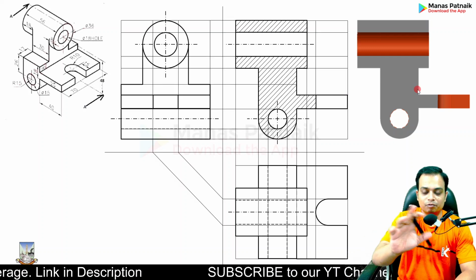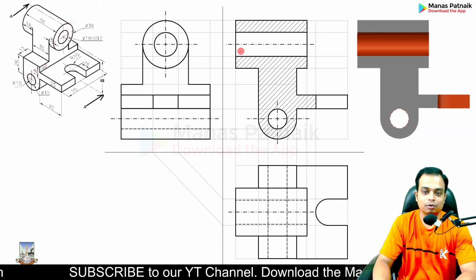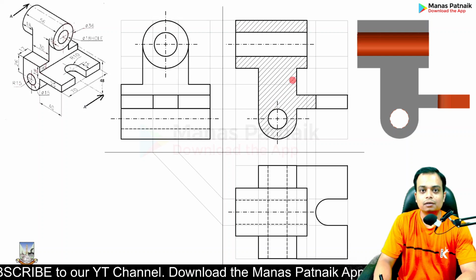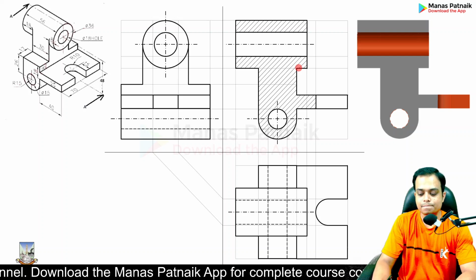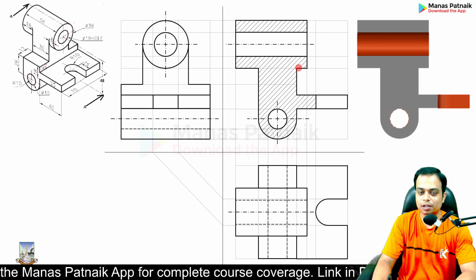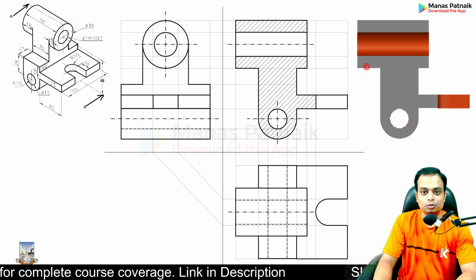Before I show you the magic, please note that all the construction work should be done very, very lightly. This is how your work should look. And in fact, while making these hatching lines, make use of a pencil which has a grayish tint or a grayish color. Keep it very light. 2H pencil, I would suggest, at an angle of 45 degrees. This is how the section looks. And finally, let me show you some magic.